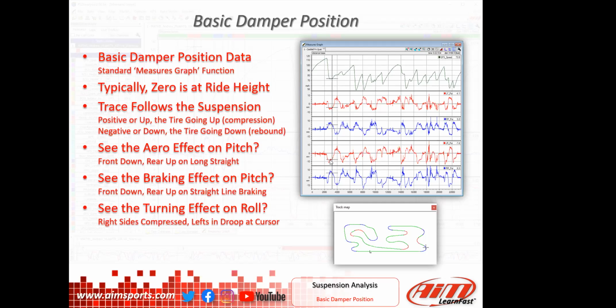You can see where he probably has released the brakes here a little bit and the car is sitting there a little bit and then starts the process as he's opening his hands. The right front has been packed in from the brakes and then stayed there because it's loaded on that right front corner and turning. And on the left front, it packed in when he hit the brakes and then transitioned into droop as it was going through the corner. Just interesting things that you can see, and how much it's moving.